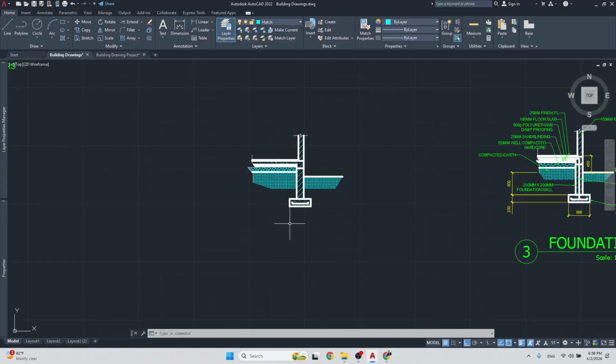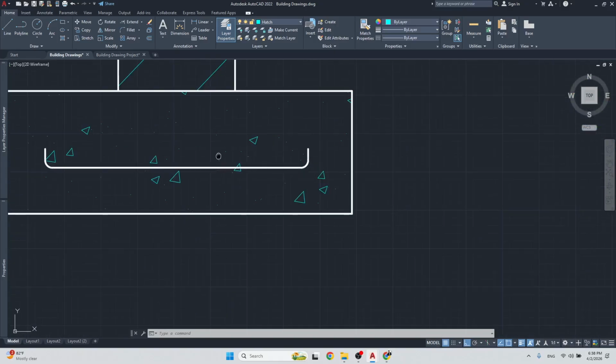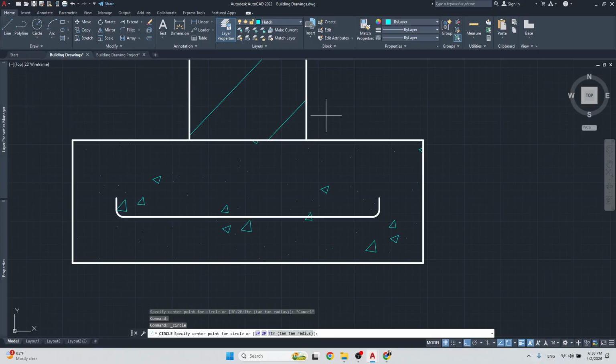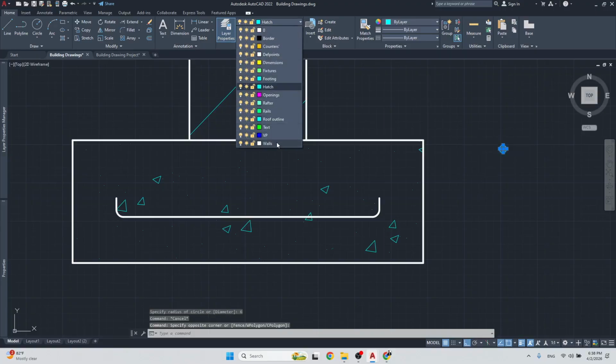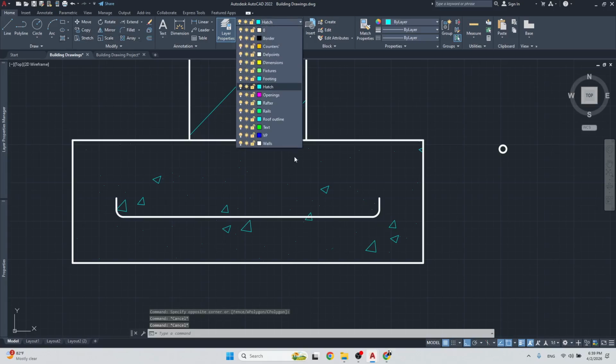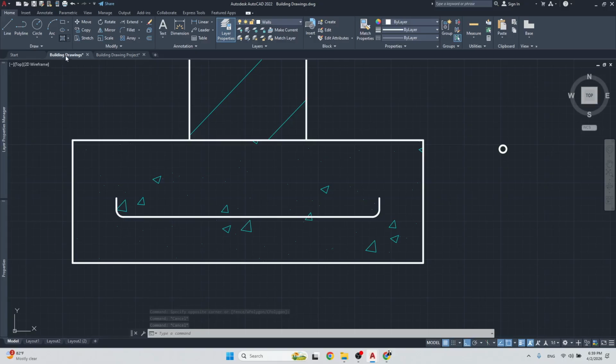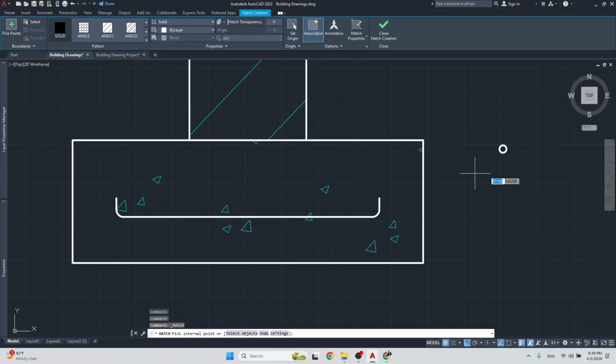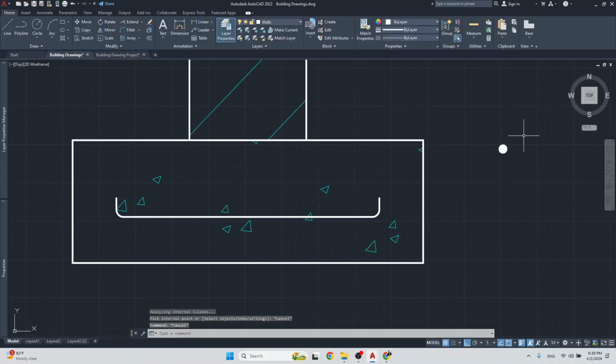All right. So let's do center radius. And we're gonna draw 12. The radius is 6, which would make the diameter 12. All right. Let me just switch this to the walls layer, and then I'm going to fill it with a solid hatch. All right, like so, like that. Bam. And then we're going to place copies of this, grabbing it by the center.